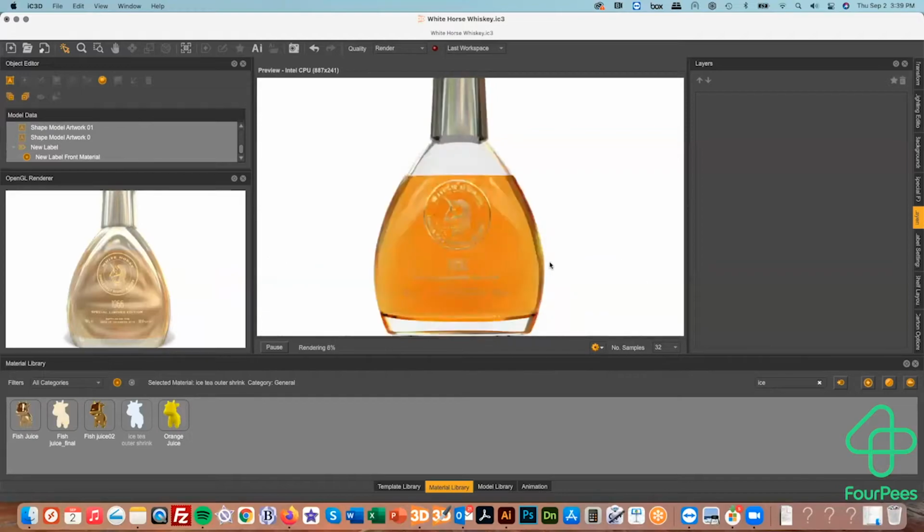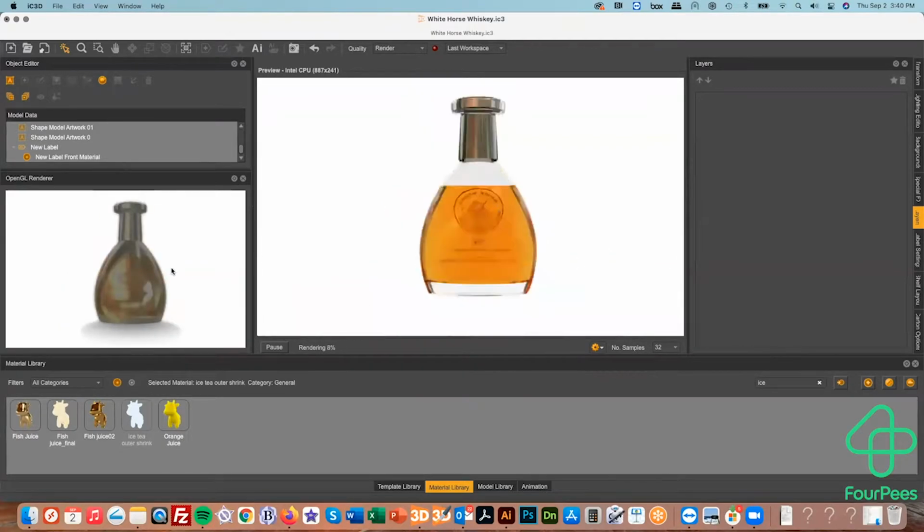So just to show you one other tool that we have, a label beautification tool inside here, and we can preview those label beautification tools I'm talking about. We've got this option inside here, hide rear facing labels and displacement. At the moment, I've got it switched on because from a marketeer standpoint, I do have an embossed effect on the back of this bottle, but I want to hide it. I don't want to have to create two separate models for two separate use cases. Marketeers don't like seeing back labels or anything through the bottle. So again, if I looked at it from the back side, you can see the displacement inside here,